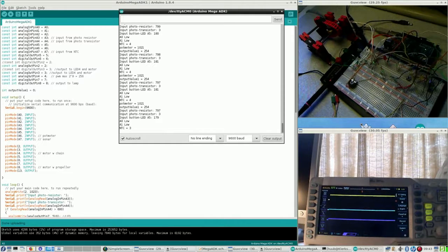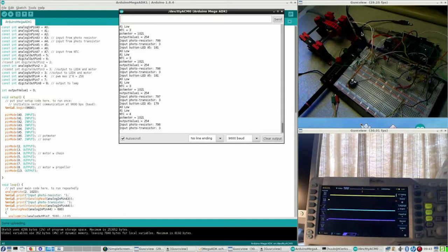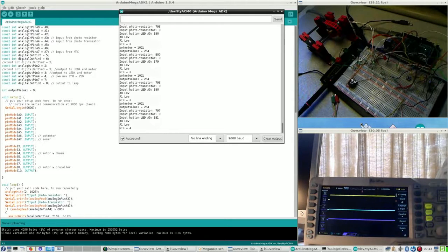So the actual signal is coming from, and let's be completely correct, from here, going here, and here's that yellow probe, which correctly shows the pulse modulated signal, then to the transistor, and then here. But there's another thing going on. The LED here, which should show activity from the transistor, is not burning.